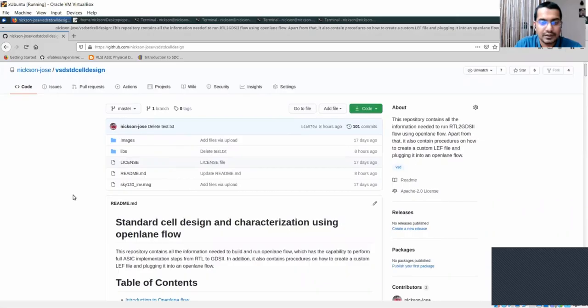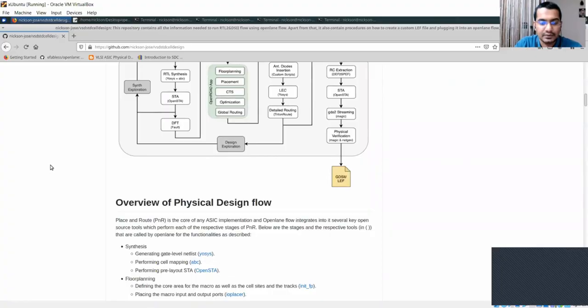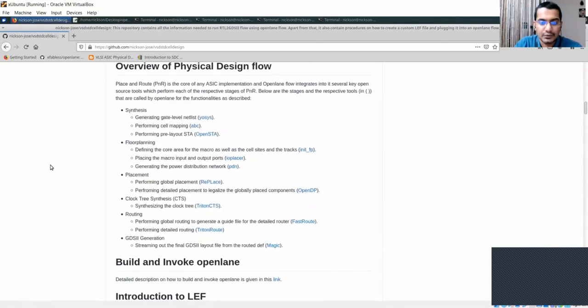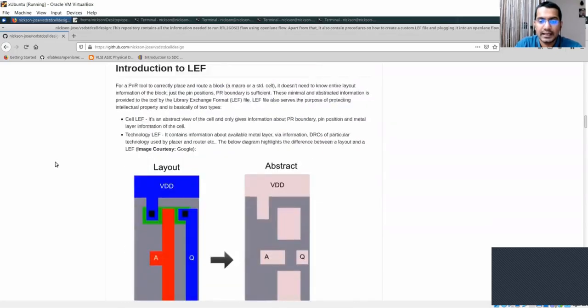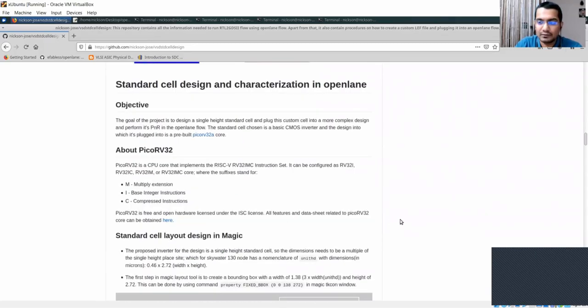So let's do that. We'll click on this one. This is basically 1.0144 on your X, 1.0144 nanoseconds, 10 raised to minus 9 is nanosecond, at y equal to approximately 1.25. Okay, so this is one point. We'll click on the other one, and you'll get the other point, 1.16277, and then take the difference between this one, and this will give you a rise delay.